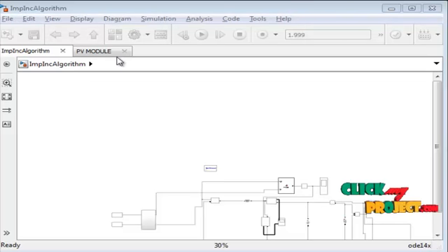Here is the Simulink library in the Matlab environment. In the Simulink library the various elements are there. According to our requirement, the elements used in the circuit are selected and dragged into the model window. Now all elements are in the model window. Then connect them as per the circuit diagram. After that, we connect the scope and the corresponding voltage and current measurement.